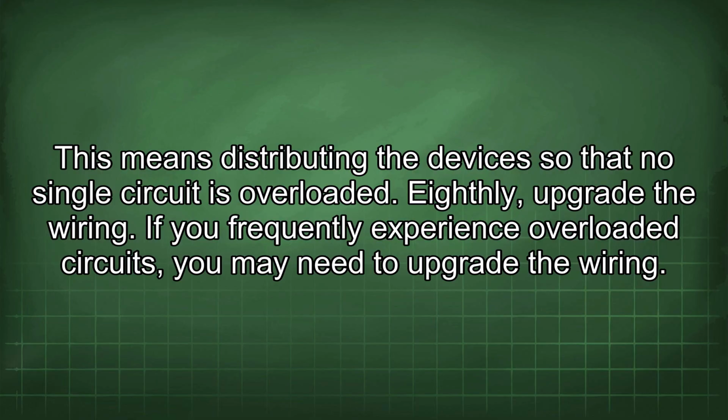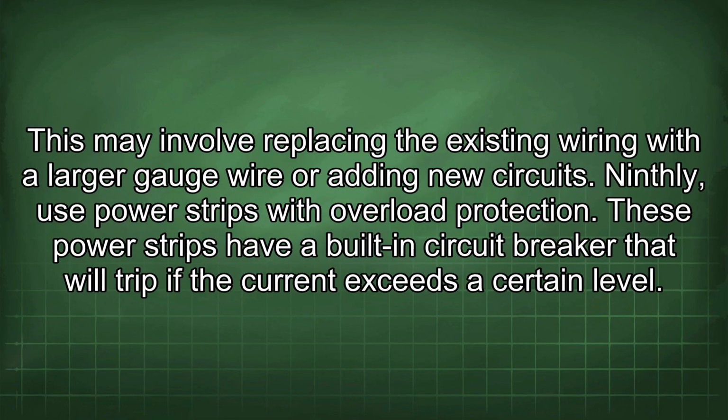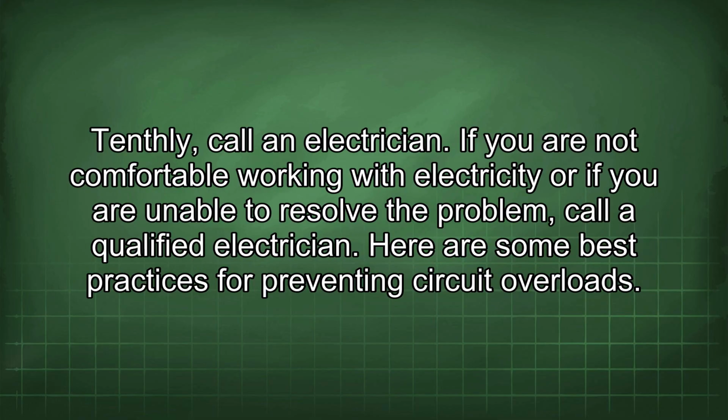Eighthly, upgrade the wiring. If you frequently experience overloaded circuits, you may need to upgrade the wiring. This may involve replacing the existing wiring with a larger gauge wire or adding new circuits. Ninthly, use power strips with overload protection. These power strips have a built-in circuit breaker that will trip if the current exceeds a certain level. Tenthly, call an electrician. If you are not comfortable working with electricity or if you are unable to resolve the problem, call a qualified electrician.